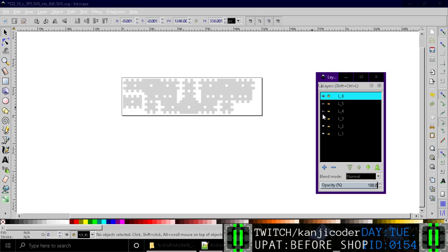The reason I don't do 100% speed is that it'd be nice to just do 100% speed and eliminate 2 variables, right? Instead of messing with speed and power, the easiest thing would be 100% speed, 100% power, and then you just figure out how many passes you need before the part cuts out, right? Because you're eliminating variables that way.